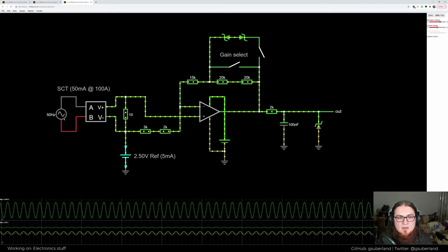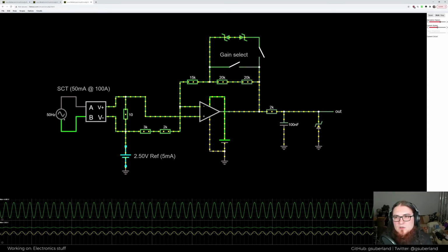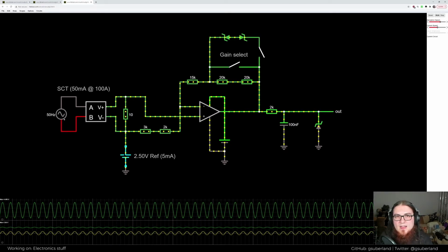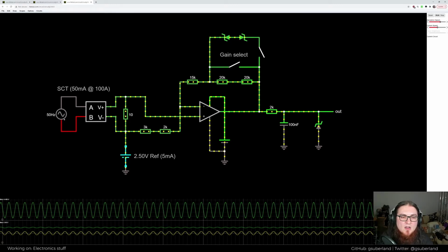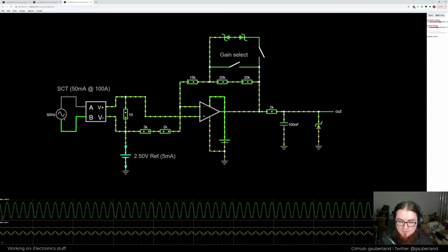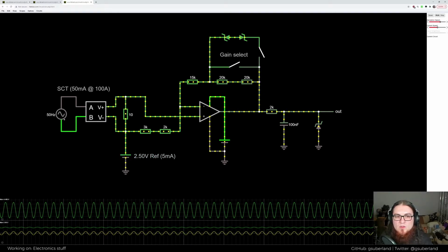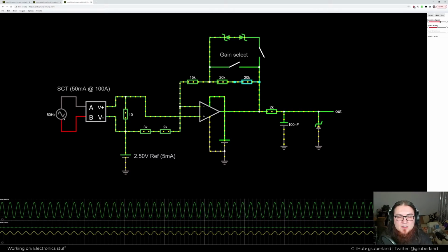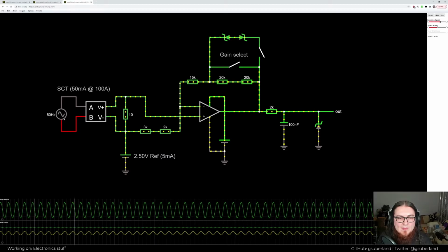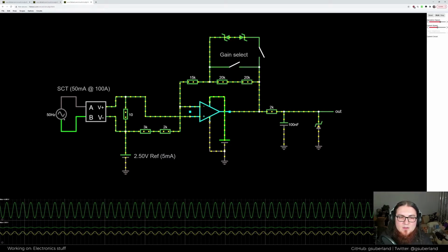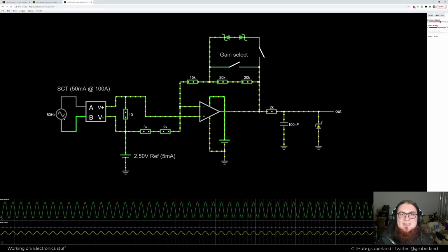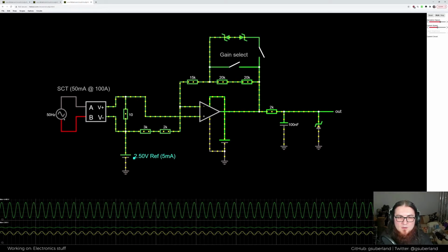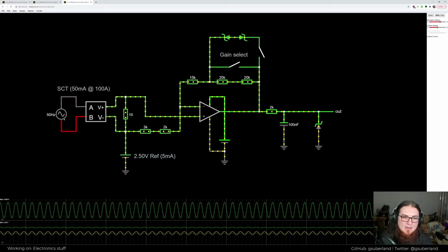Now, luckily, the voltage reference that I decided to use already had a 50 times higher current rating than I actually needed, so it's massively over-designed. These parts are cheap; they're jelly bean parts. You can just buy them for next to nothing. So picking one with a decent amount of current capability, this 5 milliamps, was enough. And consider that there's going to be 16 of these channels. Even then, it was 50 times over. So by halving these resistor values, it just gives us 25 times over, which is still way over spec. It's absolutely fine. So this can supply 25 times more current than we actually need, which is fine.